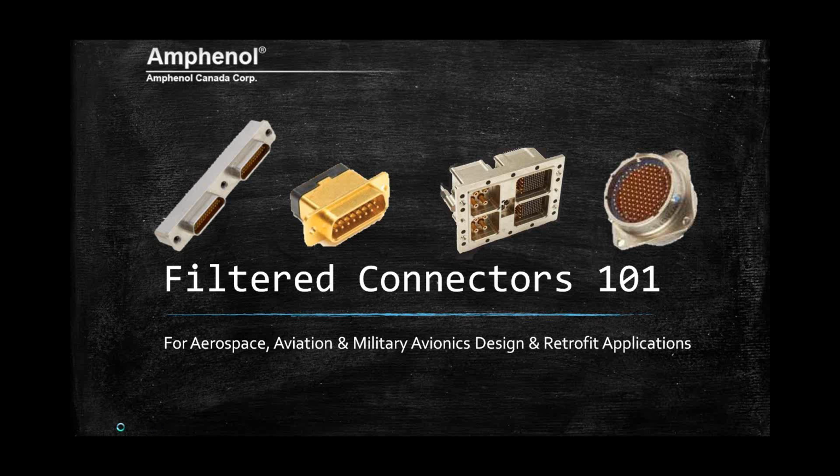When should you consider a filtered connector? Well, there's really 2 times. Obviously, in the design process, when you're laying out your system and your EMI requirements, that's a perfect time, so you get it designed in right up front and you're ready to go. However, if you've already designed something, an assembly, your system, and it's already working, but you've noticed you've got EMI issues, an EMI filtered connector can be used in retrofitting your system.